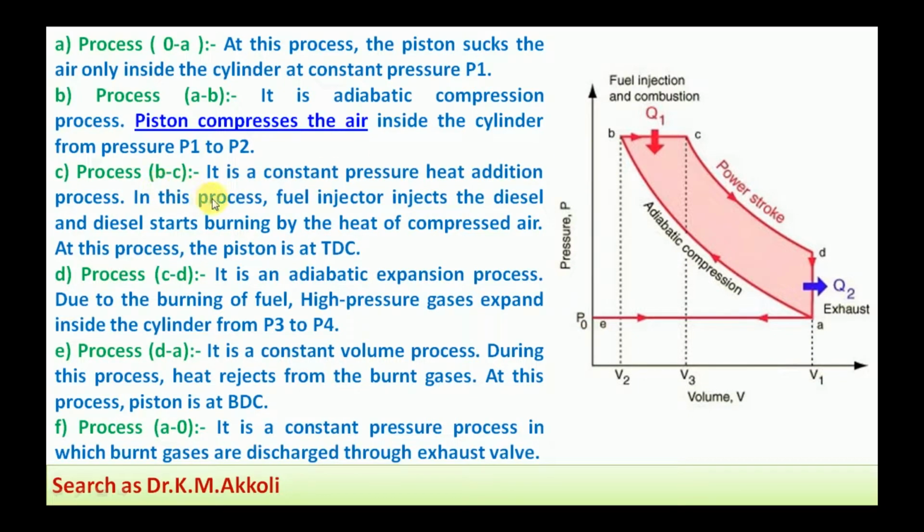Then the next process is B to C. It is a constant pressure heat addition, that is the combustion of the fuel. In this process, the fuel injector injects the diesel, and the diesel starts burning by the heat of the compressed air. At this process, the piston remains at the top dead center only.